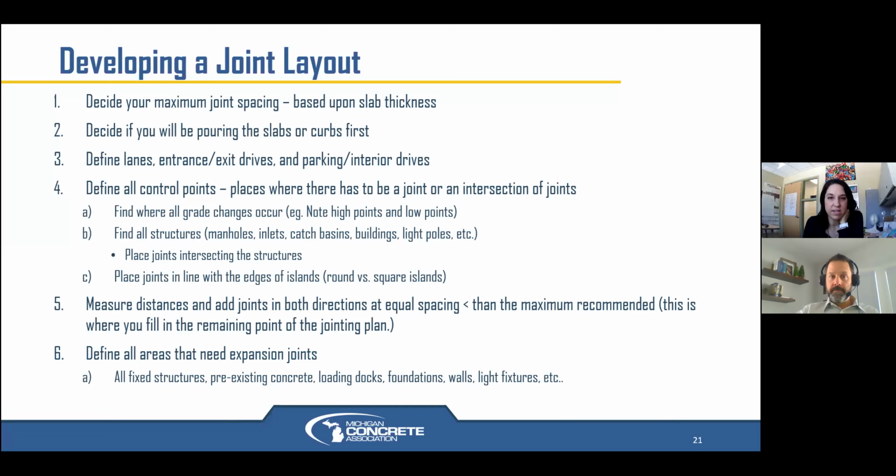Okay, so we have another one here. On my project last summer, we had issues with structures within our new concrete pavement cracking almost immediately after placement. The contractor tried every joint layout possible. Instead of using reinforcement around the structure, we isolated the structure with a sonotube and had 2 separate pours. On the second pour, the tube was removed and flexible foam was placed to isolate the structure itself. This seemed to work well and still no issues with cracking. Has the MCA heard of this?